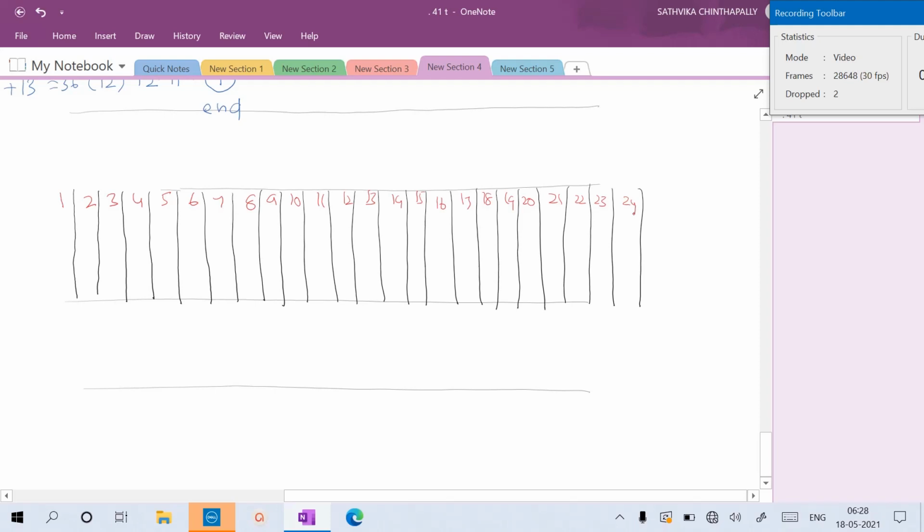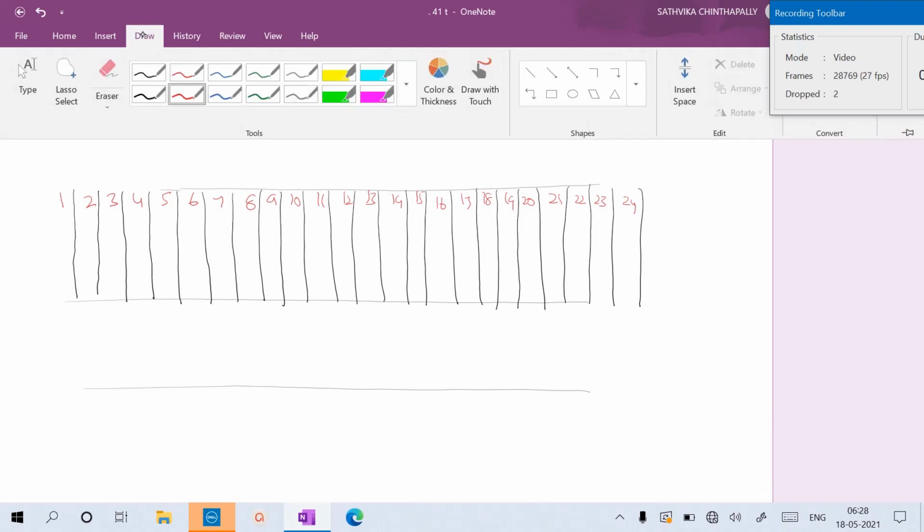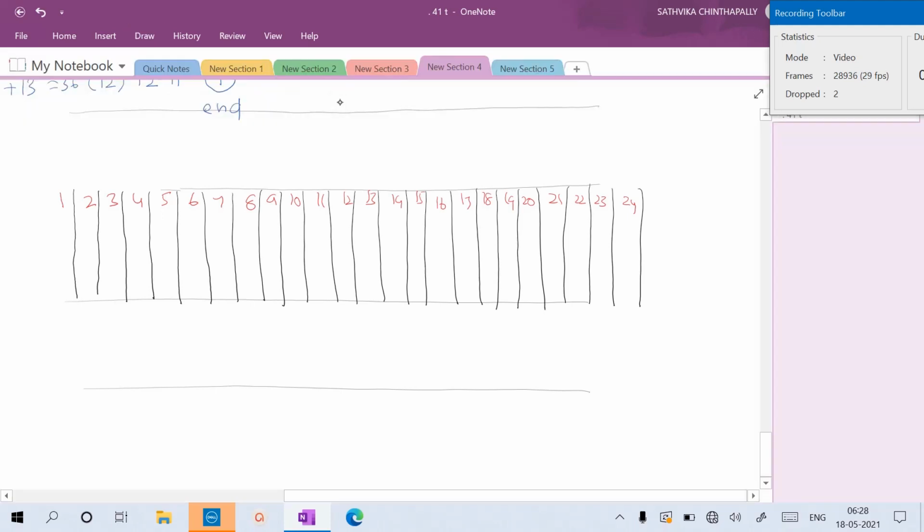And the third step, better to draw here a 2 pole machine. You make it 2 poles. So that means 24 conductors by 2, so 12 conductors, 1 pole. So you make it.